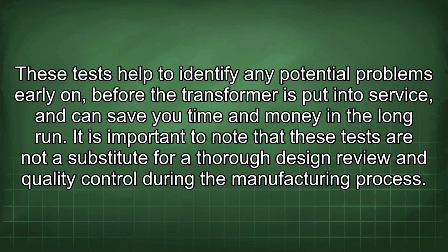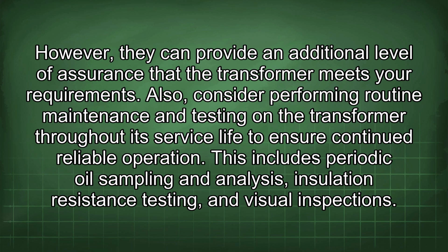It is important to note that these tests are not a substitute for a thorough design review and quality control during the manufacturing process. However, they can provide an additional level of assurance that the transformer meets your requirements. Also, consider performing routine maintenance and testing on the transformer throughout its service life to ensure continued reliable operation. This includes periodic oil sampling and analysis, insulation resistance testing, and visual inspections.